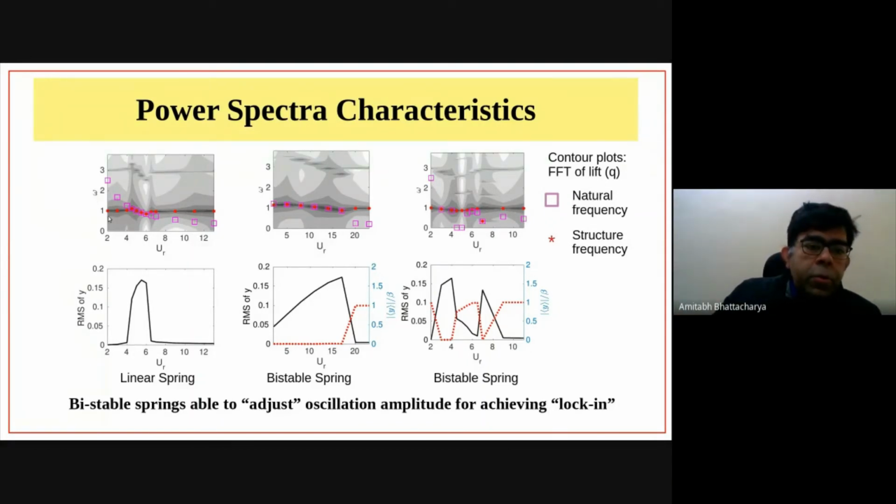So omega equal to 1 means that I have a peak at omega equals 1. For example, in your linear spring, I can see a peak here and here, at low and very high UR. The peak in the PSD seems to be at omega equals 1, which means the oscillation frequency has a peak around the vortex shedding frequency, following the Strouhal line in this case.